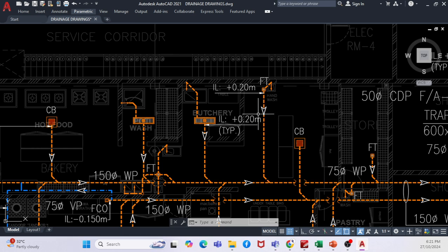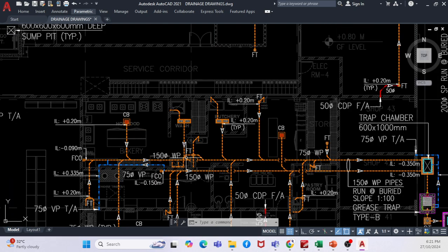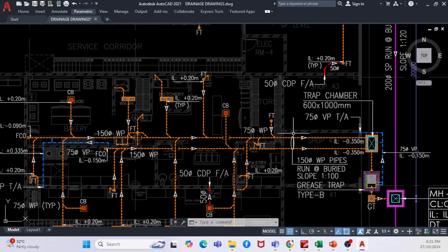You can increase any pipe size, but basically, if I have this particular area, where is my shaft location? This is my shaft location. How much increasing the pipe size will be better for drainage? My question was about decreasing after five. If you have light usage, then you can decrease, right? It depends on usage. Where I have high usage, I cannot reduce my pipe size, right?